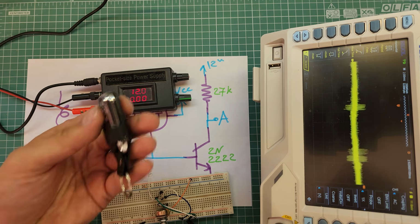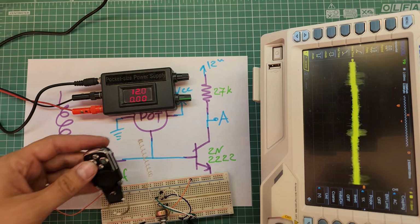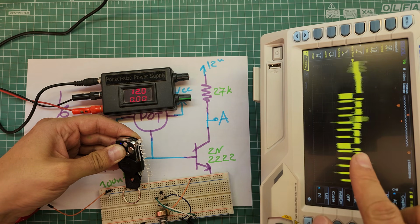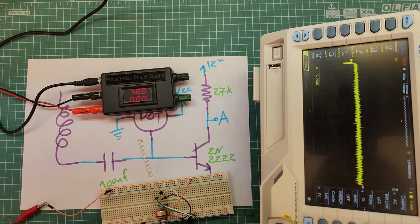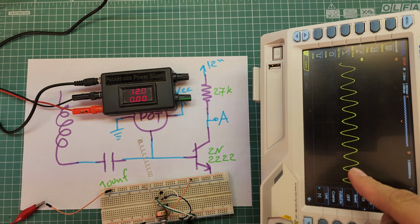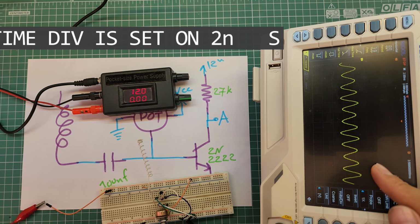I have to put the remote controller beside the wire to better receive the signal. Look here, this is the digital form of the modulated signal, and this is the analog wave transmitted by the transmitter. The frequency of this signal is equal to 433 MHz.